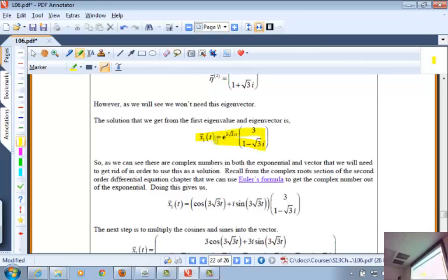that eigenvalue and eigenvector. But you know Euler's formula, e to the power i t is cos t plus i sin t, right? We've seen that in the fluid course too, right? So you use that and express the solution in this form. And so the response in the state space is going to involve sines and cosines of t, right? That will be a closed loop, okay?